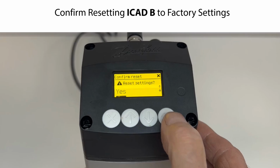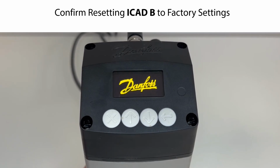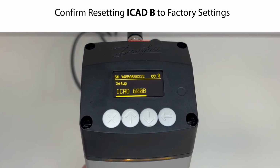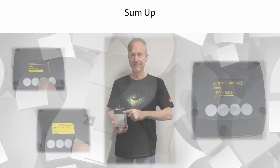Please note that when saying yes to the factory reset, this overrides all earlier configurations done and the ICAD B returns to the default factory settings. Press enter to confirm the factory reset. As seen, the ICAD B returns to the main screen and the ICAD B and valve are now ready for setup as explained earlier in this video. Okay, you have now seen demonstrated how to reset the ICAD B to the default factory settings. This supports you in doing a fast, easy and flexible ICAD B and valve setup.